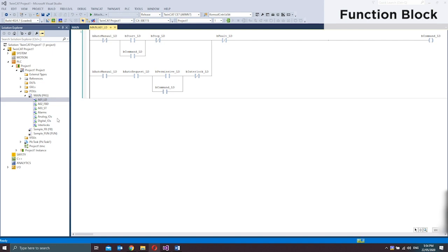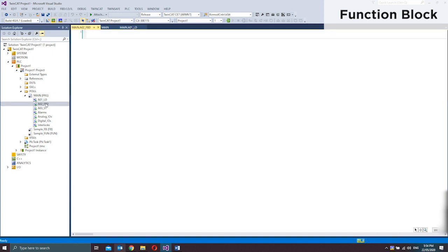It is similar to ladder because it also has networks, and the logic runs from left to right. The difference is it only contains block boxes that do Boolean operators such as AND logic or OR logic, and also math comparisons such as equal, add, divide, multiply, greater than, less than, and so on. The variables to be compared can be seen on the left side of the block, and on the right side is the output. If the condition is satisfied, there will be a true value on the output of each block. Standard function blocks can also be used here, such as timers, triggers, and counters.